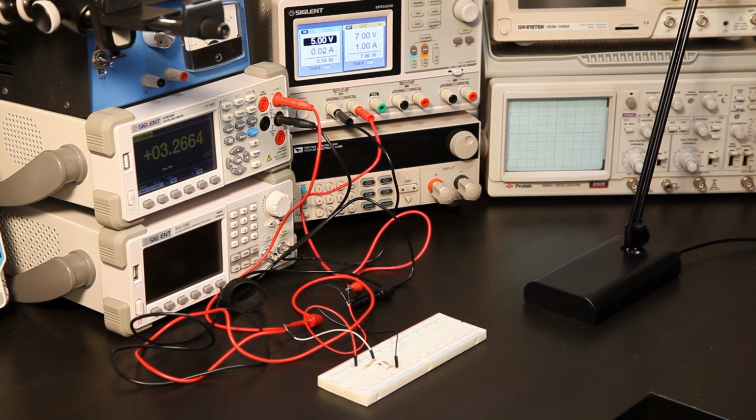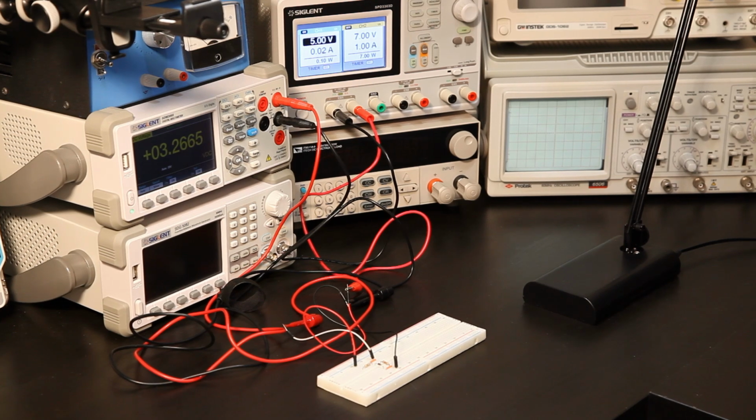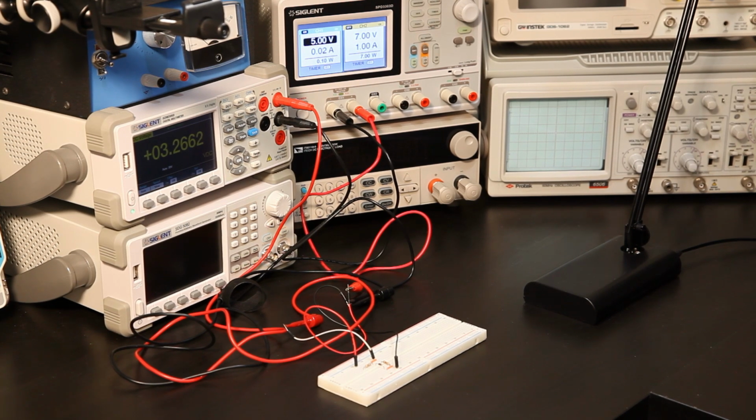I want to show you how a Zener diode regulator performs. This is essentially the same circuit, but different values. The Zener diode that I have is 3.3 volts, and IZT is 20 milliamps. And I've set it up with a 1 kilo ohm load on a 5 volt input supply. So with 3.3 volts across the 1 k ohm resistor, that's going to be about 3.3 milliamps.